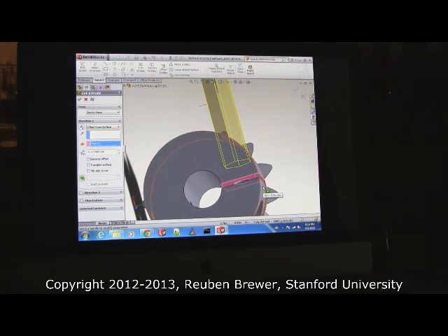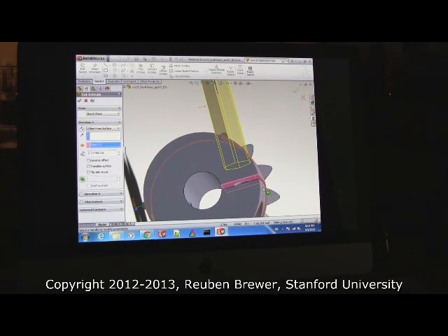Kirk, you doing okay? Last time was it also the one closest? Yeah, but in both cases, it's the one closest. Okay. The reason being, we're going to put little hex nuts in there, and we need enough material to make sure it doesn't just rip through the plastic. Okay. So you're going to be defining it from the nearest surface so the hex nut doesn't rip through.